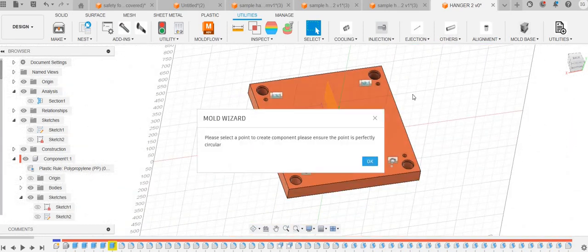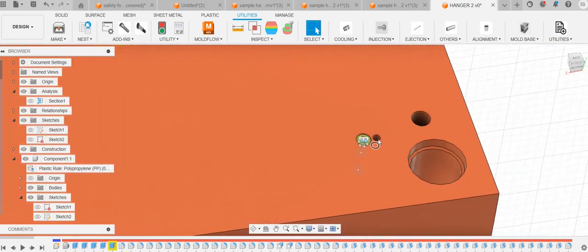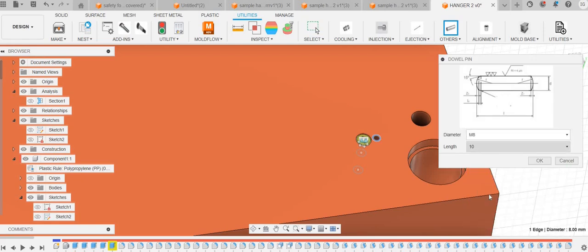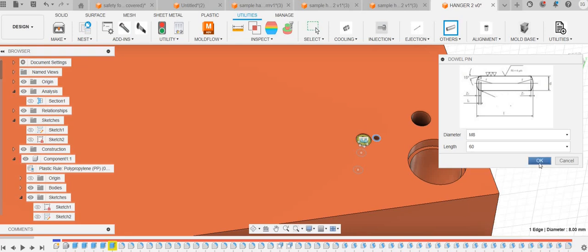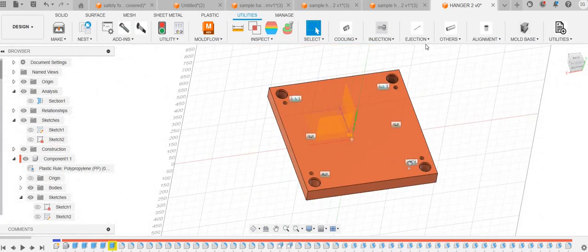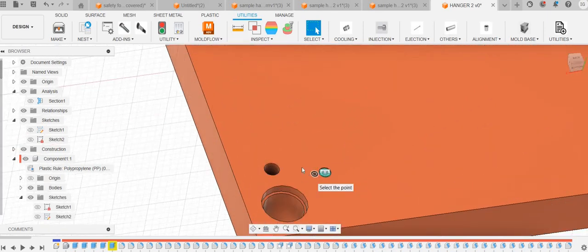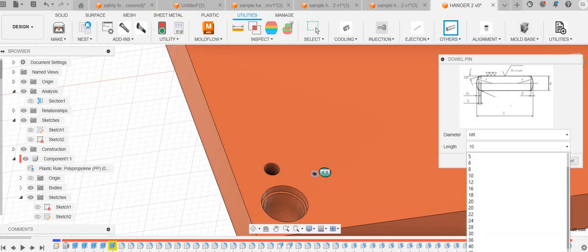So the way to do it, if you want to create multiple single components, is to just repeat the command or the add-in. If you use an array, it won't recognize it as a new component in your design. So hence we are going to repeat this four times. Okay. 60.